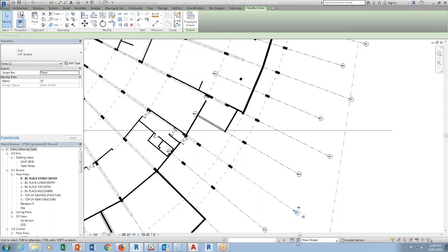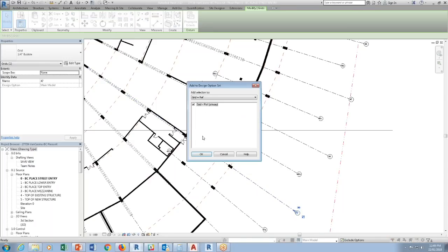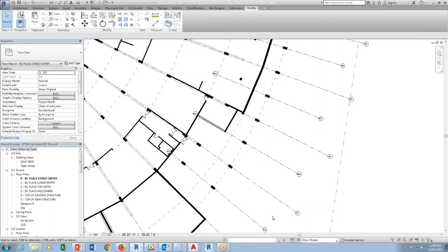Work set, what it does is that if you put them in here, let's say I'm going to put this under referencing grid. Could you not then own the work set and not let other people edit? Nah, I don't want to do that. Okay, just not a good practice. It's just that sometimes it can lead to corruption. I don't want to do that.